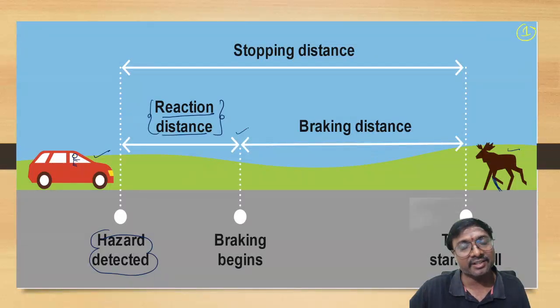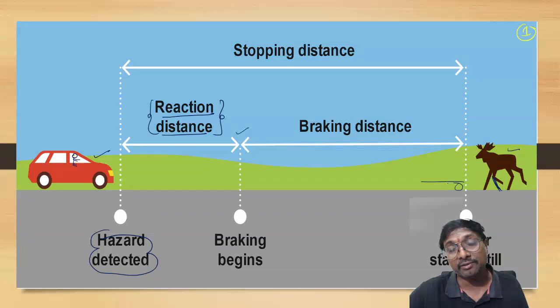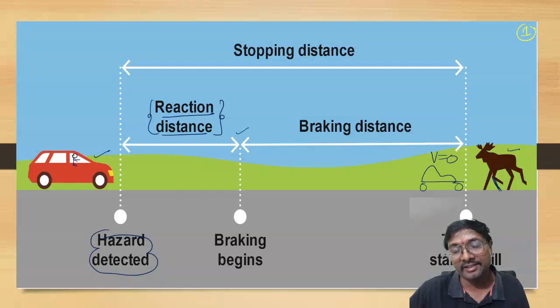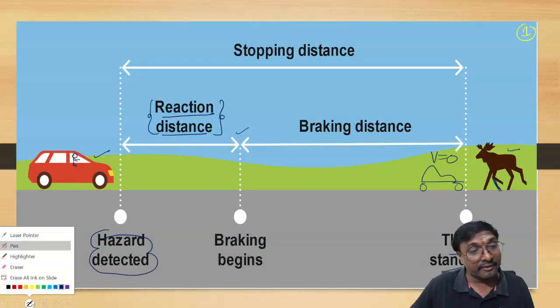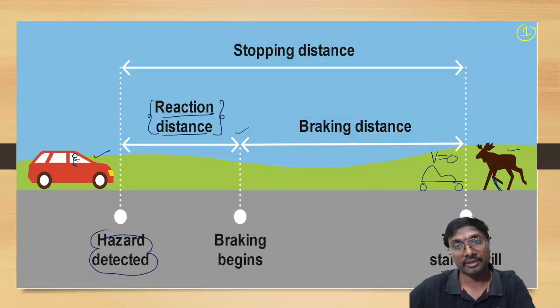After that, the decision we take is to apply brakes. After this entire thinking is over, we start applying brakes. But can you apply sudden brakes? If you apply sudden brakes, it will become a doom situation, and we are not making a doom movie here practically. So we have to apply the brakes slowly. We travel for some more distance while applying the brakes, and then your vehicle comes to a complete stop just in front of this object. That is your critical-most condition.